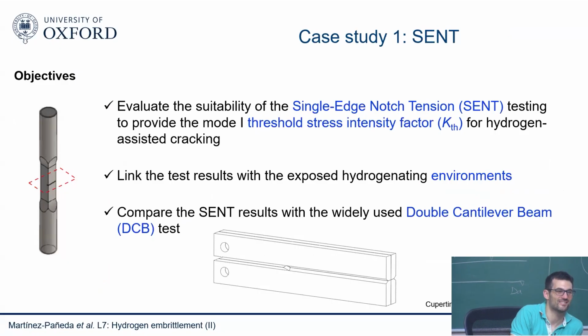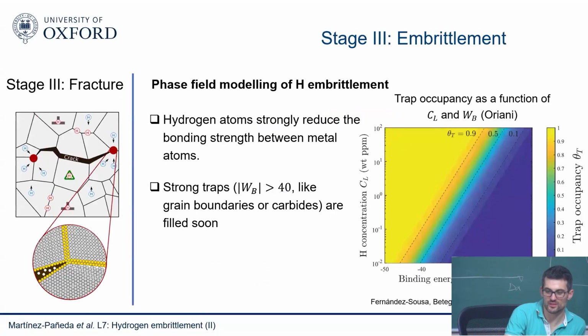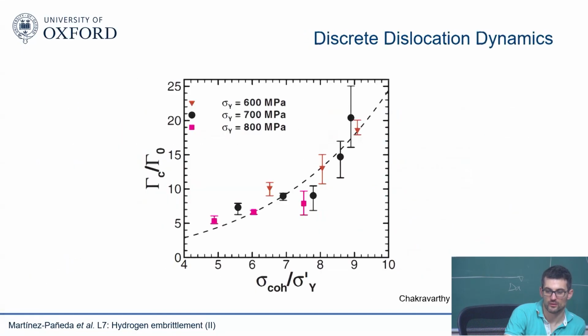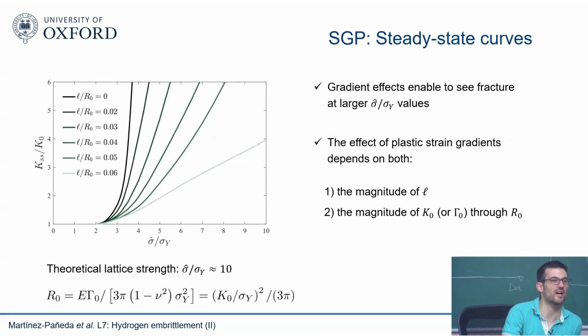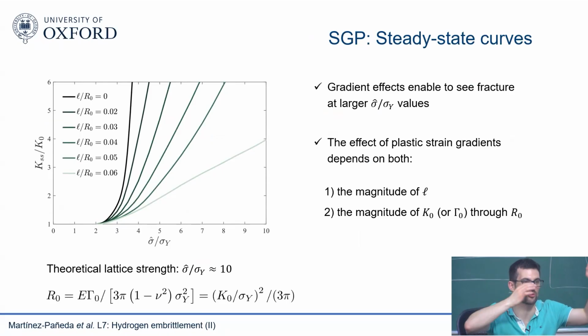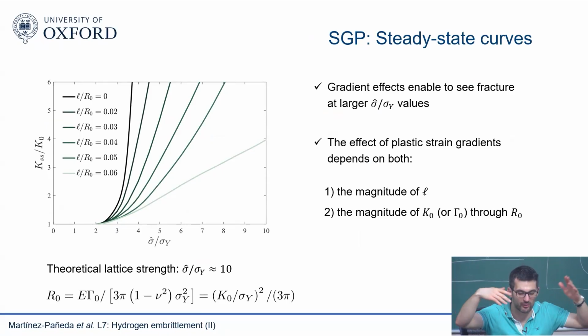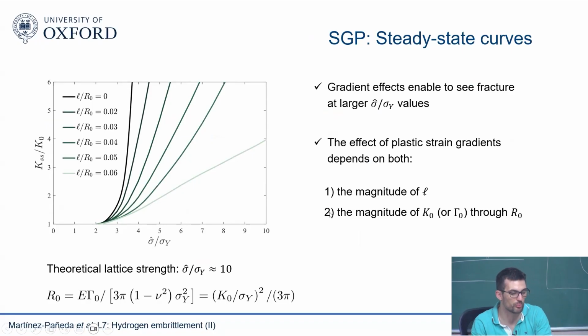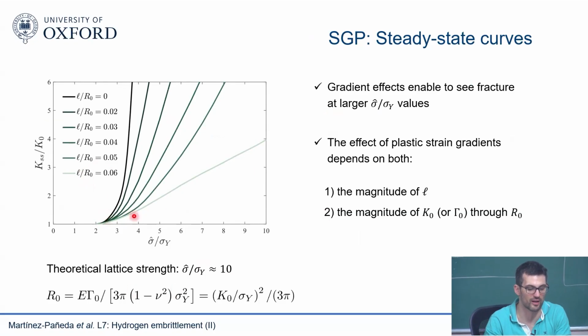Again, I'm a little bit stuck on GC, but in all these simulations, is GC a function of the hydrogen concentration? In these ones that we showed here, no. This was a study in general where we said all brittle fracture processes will somehow lower GC, but we don't know how much lower. Then you need to put in the numbers and say, if I put here the right number, is this R0 low enough that I'm in this plot, or am I somewhere here, and so on.